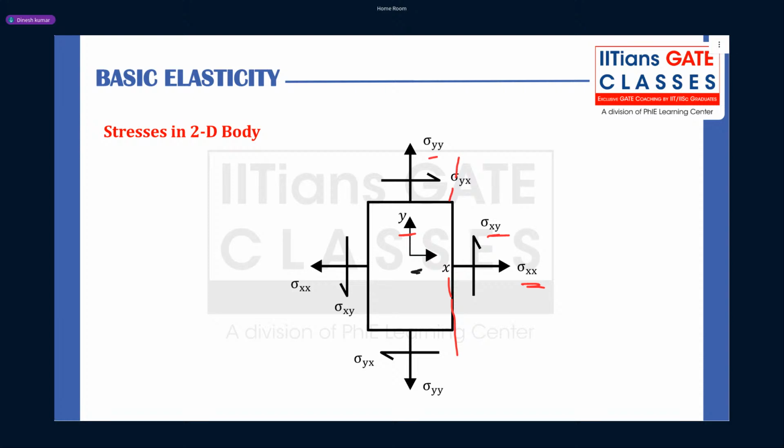Now guys, on this plane your stress is sigma yy, going in the positive y direction, so the corresponding shear is going in the positive x direction, which is sigma yx. Same way, on the bottom plane, is it plus y or minus y? Minus y, right?